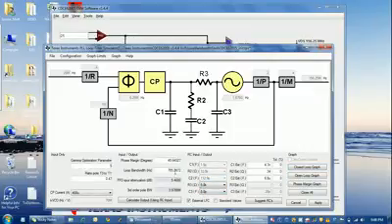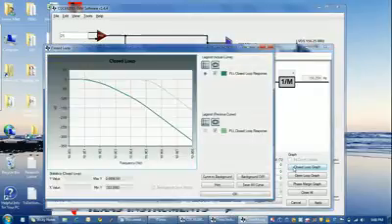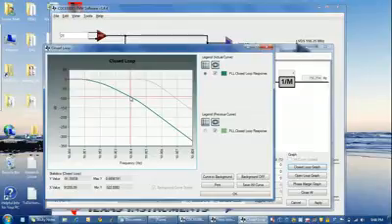Now let's try to get a much lower bandwidth using a loop filter with external RC components. We want to click the checkbox here if we want to restrict the recommended components to standard values. Once again, let's look at the closed-loop response. Here we see our previous filter in the background and can compare between the two.